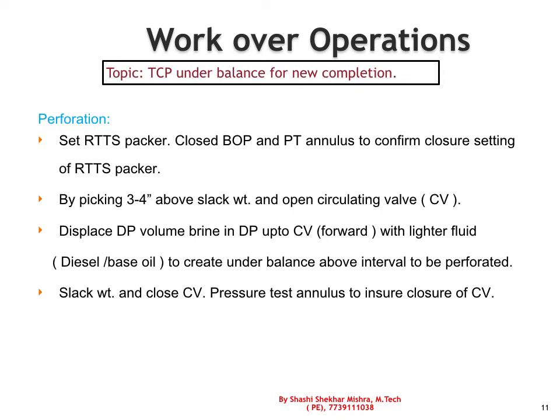Once the gun is placed on depth, we will set the RTTS packer, close the BOP, and pressure test the annulus to confirm that the packer has been set.